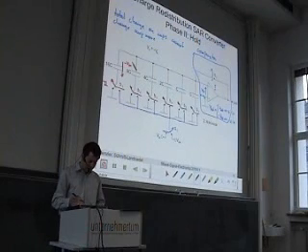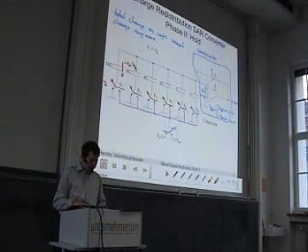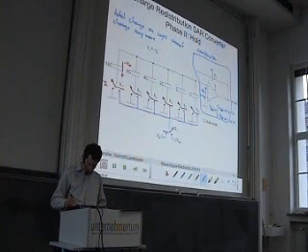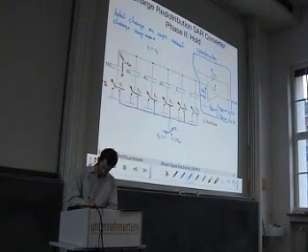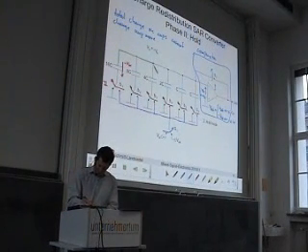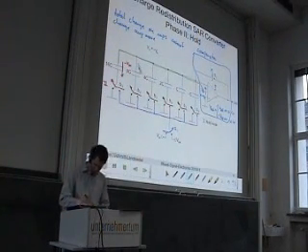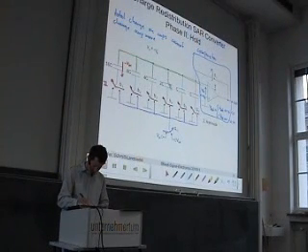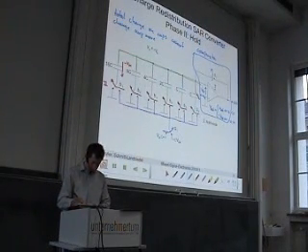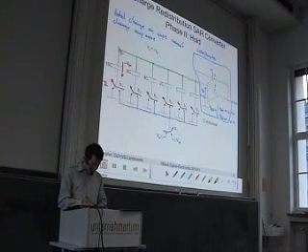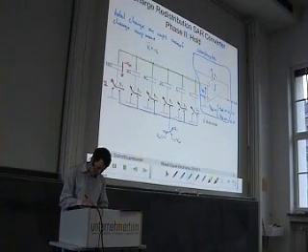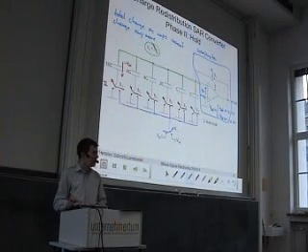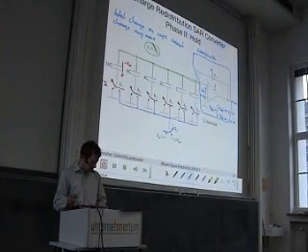And this means that the potential of this node X here, which we call Vx, this Vx is equal to the voltage drop across the cap here. So we have, as already stated here, Vx equal to minus Vin. Good.